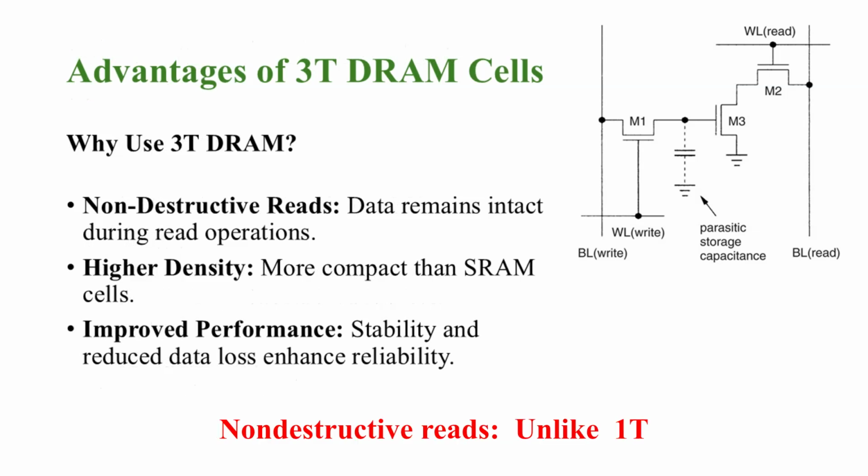3T DRAM offers several benefits. Non-destructive reads. Unlike 1T DRAM, reading doesn't erase stored data, enhancing reliability. Higher density. It is more compact compared to SRAM, allowing for larger memory arrays. Improved performance. Additional transistors in the design provide stability and reduce the risk of data loss, making it ideal for critical applications.